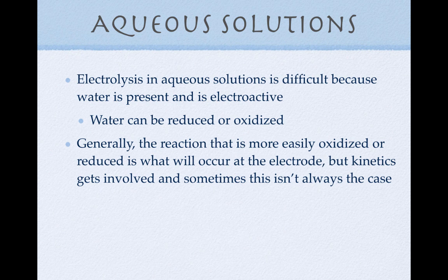This is something that was very common many years ago with recharging car batteries, or trying to jump a car battery. Essentially what you're doing when you jump a car battery is applying an overpotential to try to get that battery to recharge a little bit, and in doing so you can accidentally start to electrolyze the water and start to make hydrogen gas, and again, if you get that spark around that hydrogen gas, you can get an explosion.